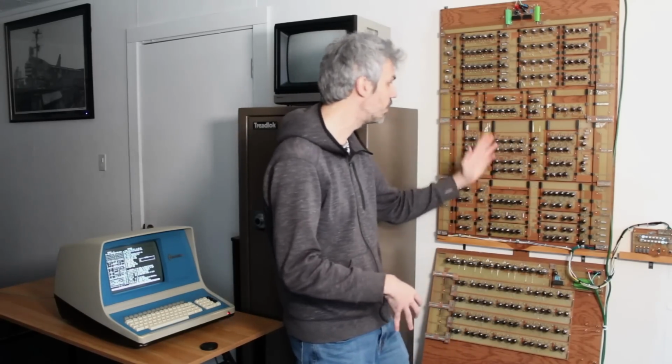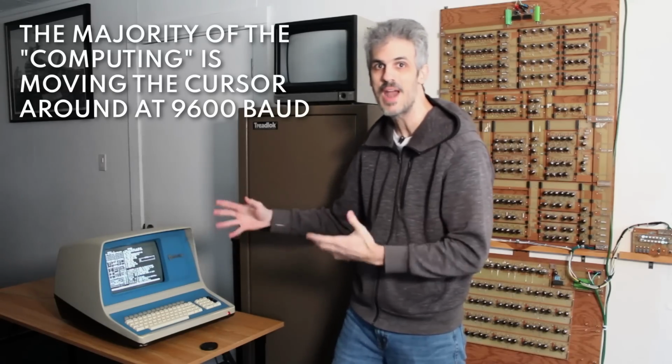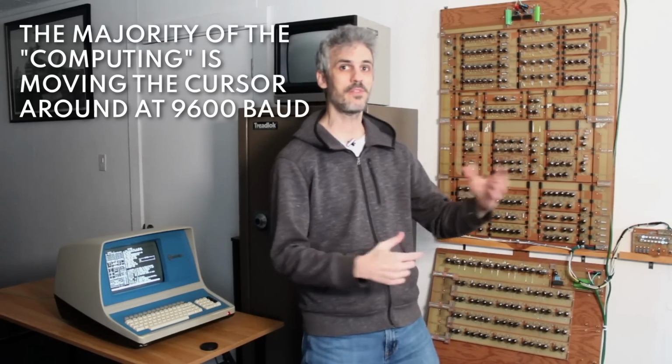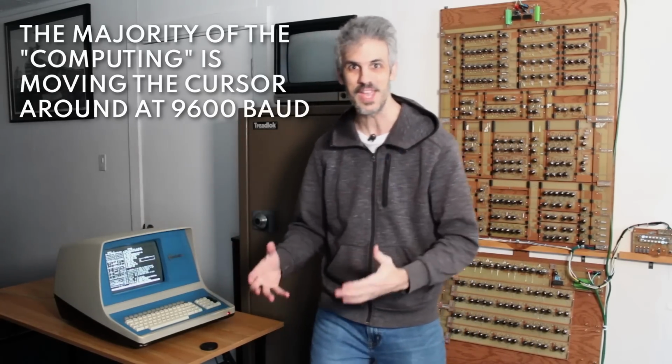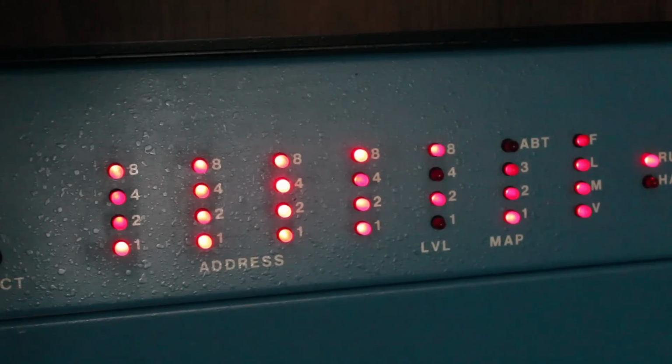And that makes total sense because the way that the real processor works is that everything is done on the rising edge except for latching the result register and the carry register. That's the only thing that's done on the falling edge. So the amount of computing that the emulator has to do on the rising edge is considerably more than the amount of computing it has to do on the falling edge. And that's something that we can visually see in the blinking lights.